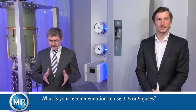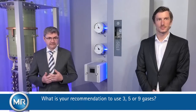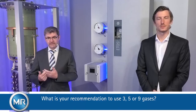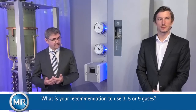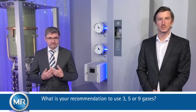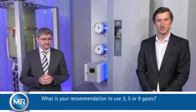With the DGA 3 system or the DGA 2 system, you have a quite simple, robust system for early warnings and to get the first information that something is happening. You can't do deep analysis with this system, no diagnosis. So you get the information that something is happening in your transformer, for example. Then you can decide to take an oil sample, send it to your oil laboratory, and do all the analysis that laboratory can provide you with, and get into a deep root cause analysis. That is one way to go.